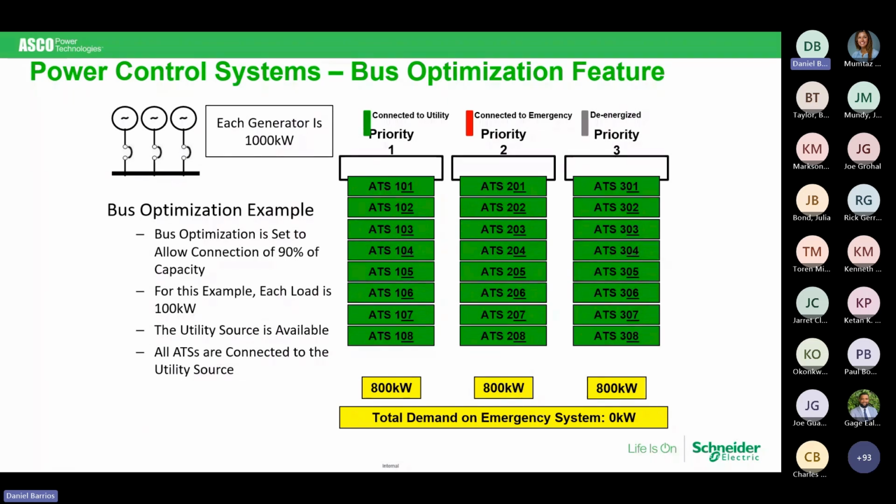So if I take that 800 amps and I say, okay, fine, I'm going to say this is a 400 kW load and hard code that into the ATS, that's the number I'm using to know if I have to add or shed that amount of load off of the generator. The other term that we're going to delve into is called dynamic bus.